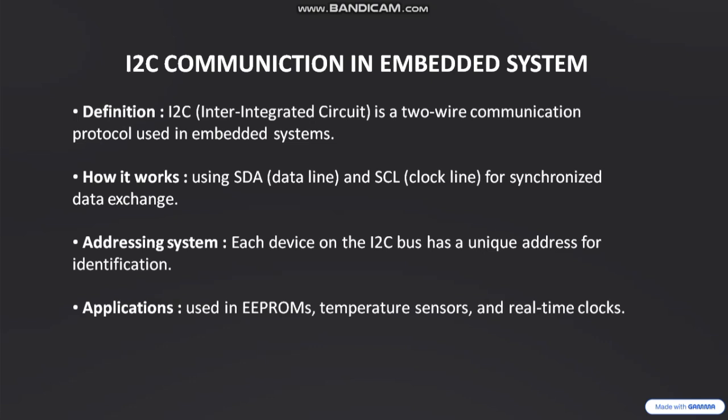Next, I2C communication. I2C is a serial communication protocol that uses only two wires, SDA and SCL. SDA is used for data transfer and SCL is used for clock synchronization. Each device on the I2C bus has a unique address. This allows multiple devices to communicate using the same wires. It is widely used in sensors and RTC modules.